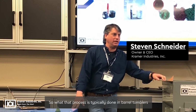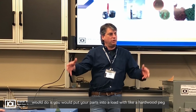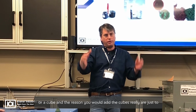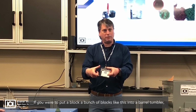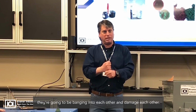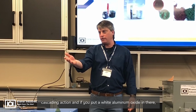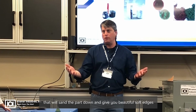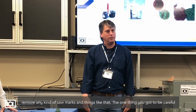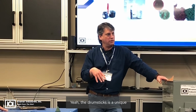That process is typically done in barrel tumblers, and it uses hardwood media. What you would do is put your parts into a load with a hardwood peg or a cube. The reason you would add the cubes is to allow for a softer action. Remember that cascading action we were talking about? If you put a bunch of blocks like this into a barrel tumbler, they're going to be banging into each other and damage each other. But if you fill that space with smaller media, you get this nice cascading action. If you put a white aluminum oxide in there, or a black silicon carbide, depending on the color of your wood, that will sand the part down and give you beautiful soft edges, removing any saw marks and things like that. You've got to be careful not to use too abrasive a process if you have an intricate design, because it will wear down some of that design.